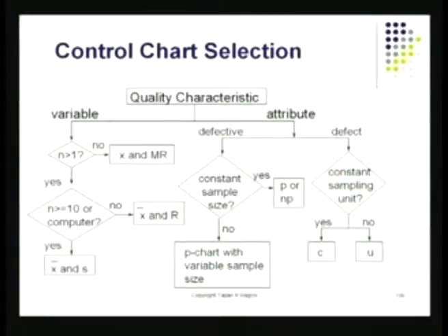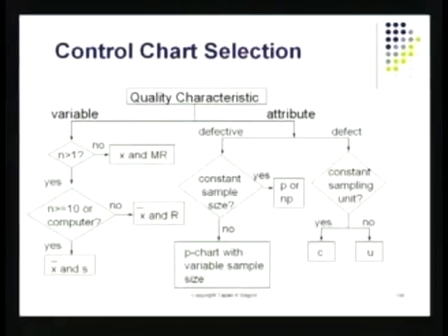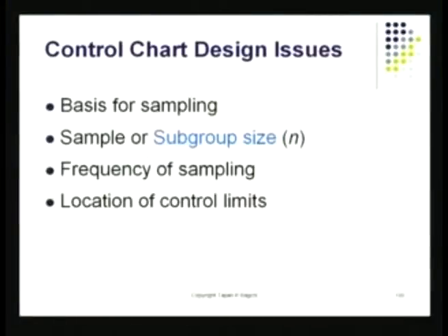I should be using what is called the U chart, which is like, in that sample, how many defects did I find? In that sample of size 3 or 5 or 2 or 0, not 0 of course, 1, how many defectives did I find? How many defects did I find? Once I know that, I'd be able to use the U chart. And the U chart runs very similarly to the C chart there.